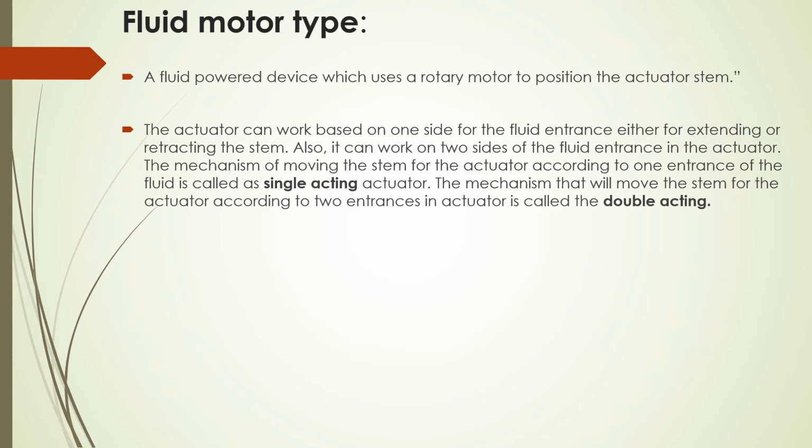The mechanism of moving the stem for the actuator according to one entrance of the fluid is called a single acting actuator. But if we have the mechanism that will move the stem for the actuator according to two entrances, the actuator is called a double acting.